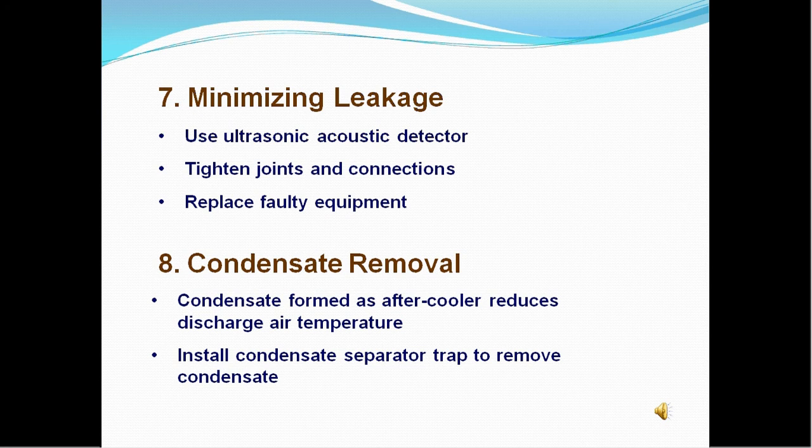Condensate removal. After compressed air leaves the compression chamber, the compressor's aftercooler reduces the discharge air temperature well below the dew point. Therefore, considerable water vapor is condensed. To remove this condensation, most compressors with built-in aftercoolers are furnished with a combination condensate separator.